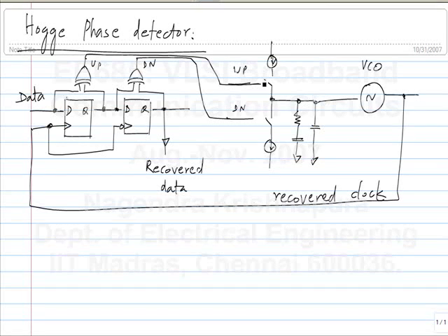Okay. So density factor is defined so that for alternating data, for 1010 data, the density factor is 1. That is, in every bit transition, there is a transition. In every period, there is a transition. And in random data, obviously, that's not the case. So if you have purely uncorrelated random data, then the density factor will be half. Okay. So either bit is 1 or 0. It's the same as saying either you can have a transition or you don't need to have, you can have a case with no transition. Okay.